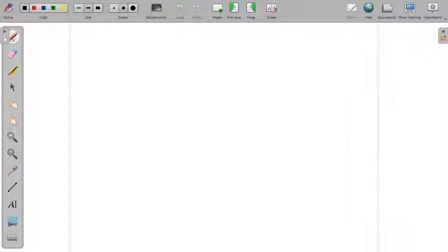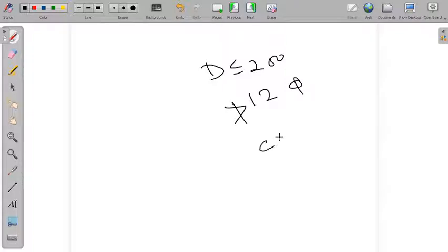Again I am saying, when the least lateral dimension is less than or equal to 200 mm, whose main reinforcements are not more than 12 mm, in that case a clear cover of 25 mm is accepted.